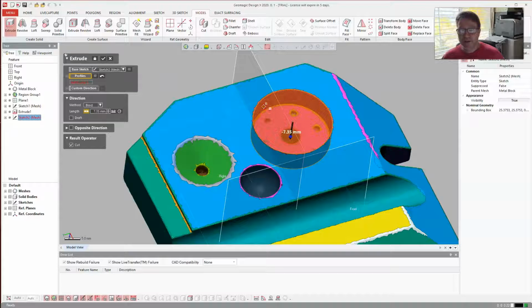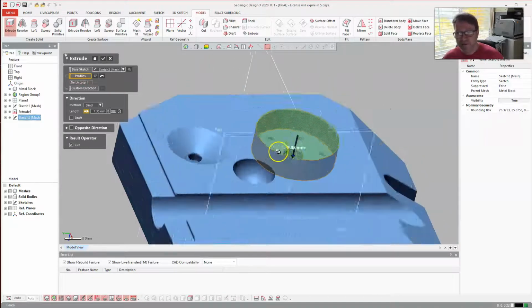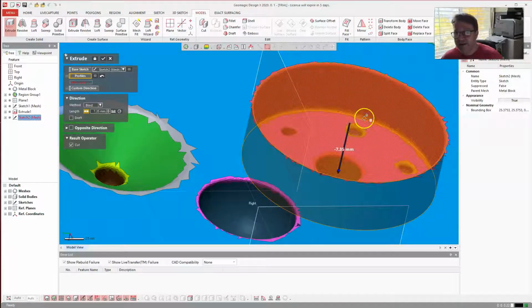And then, oops, let me scroll this around. Now, getting this exactly right, since this is all mesh data, there's no surfaces, so I can't do extrude surface. You know, that'd be the best. So unlike SolidWorks, it can't do that. But what I can do is kind of like when we did our PDF to part, where we had one dimension, and we dimensioned from the pictures after scaling that one picture, or the three views of the pictures. Well, we can scale this by grabbing this and guessing where it is.